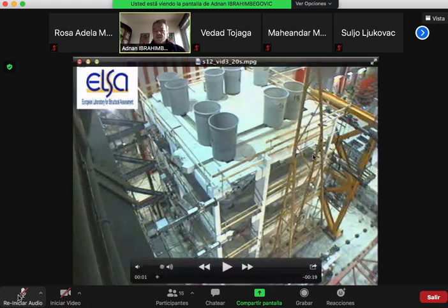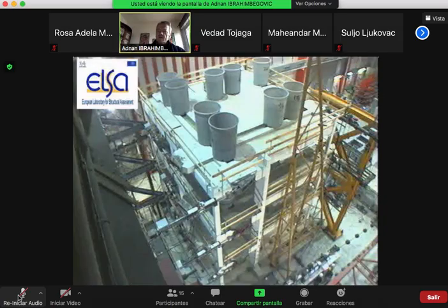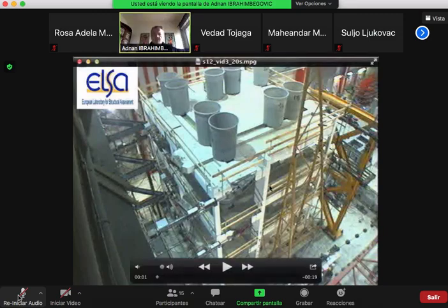And instead of a shaking table, there is something called a reaction wall. In other words, instead of simulating the earthquake by moving the base of the structure, like I showed you for this masonry structure, here they can take a real-life structure. This one, selected here, is a typical villa, a typical house of rich people in Greece.